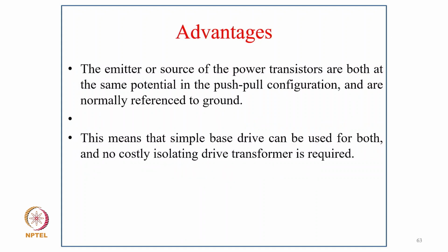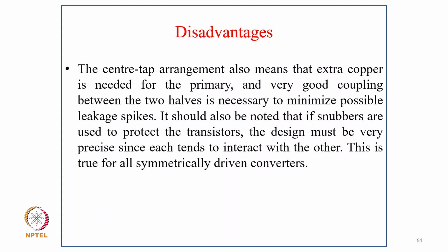And the emitter or source of the power transistors are both at the same potential in the push-pull configuration and are normally referenced to ground. This means that a simple base drive can be used for both, and no costly isolating drive transformer is required in many applications.